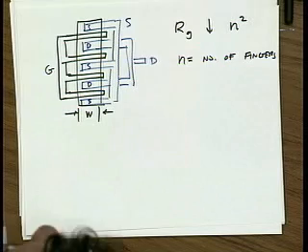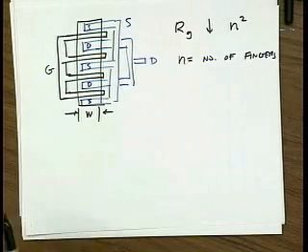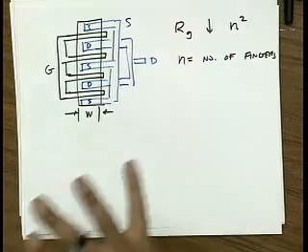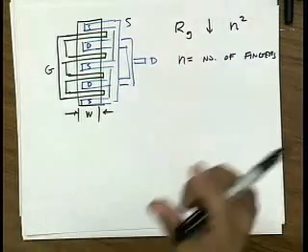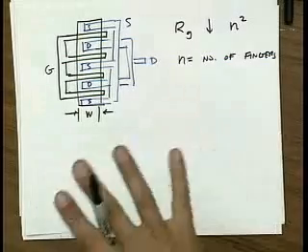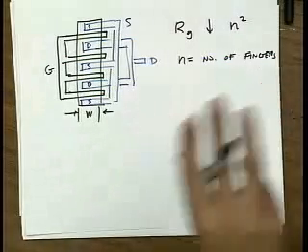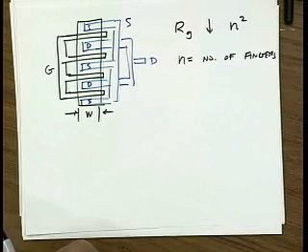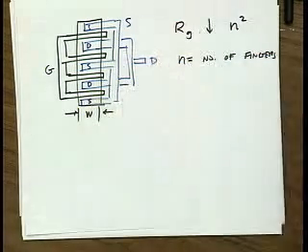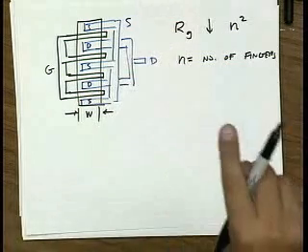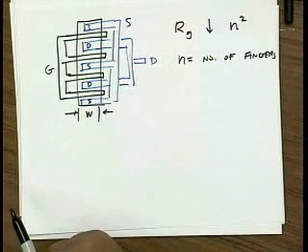So if you're using somebody's process and they call it an RF process, then when you instantiate a transistor, it'll have all these parameters, like how many fingers do you want, what's your W, and then it'll go in and try to fit as many contacts as possible to reduce the resistance. So it's very highly dependent on the design kit. If you're ever in doubt, you can just put down transistors in parallel. So use the M value, the multiplicity.